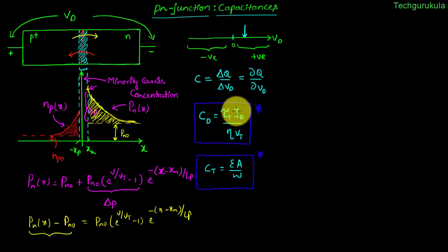Let me compare both the capacitances, how they are changing with respect to the applied voltage across the diode. In order to do that, CD can be said to be directly proportional to exponential of the diode voltage over Vt, and we can add eta as well, which means the capacitance would exponentially increase as Vd increases, assuming Vd is positive.